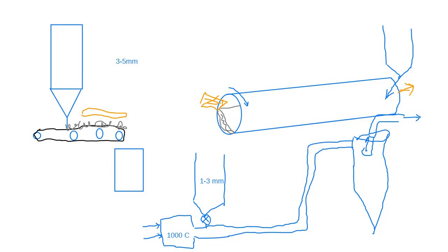Right, and then the other thing, you can see how very clearly I've marked this as a horizontal bit of piping, and this is a vertical bit of piping. Yes, this is a vertical bit of piping, because you can't do them at an angle. In pneumatic conveying systems, it will always be horizontal or vertical. With horizontal, you will get some stratification, but if you've got high enough and turbulent flow, you will get a denser area at the bottom, but it will not settle out.